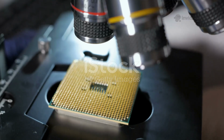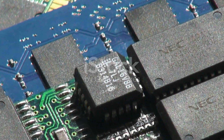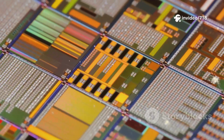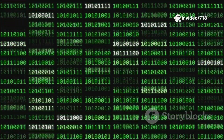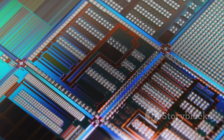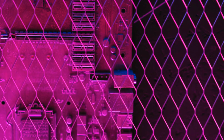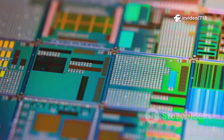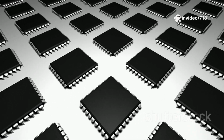Let's zoom in even further, right down to the microscopic level. What is this DRAM actually made of? As we mentioned, the fundamental unit of DRAM is the memory cell, and its job is to store a single bit of data, a 1 or a 0. These cells are arranged in a massive two-dimensional grid on the silicon chip, like a gigantic, perfectly organized spreadsheet. Each cell has a unique address, like a house on a street, defined by its row and column number.